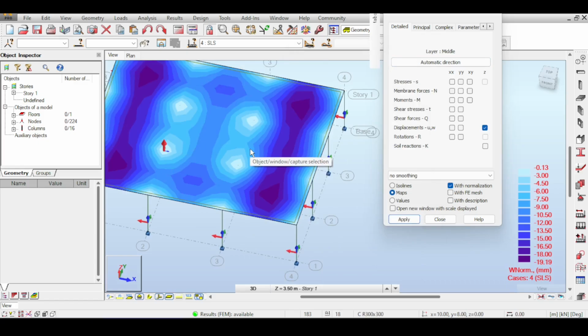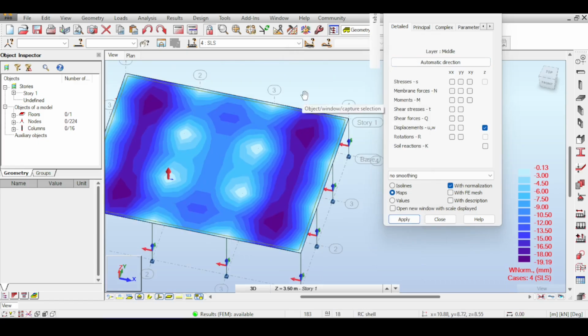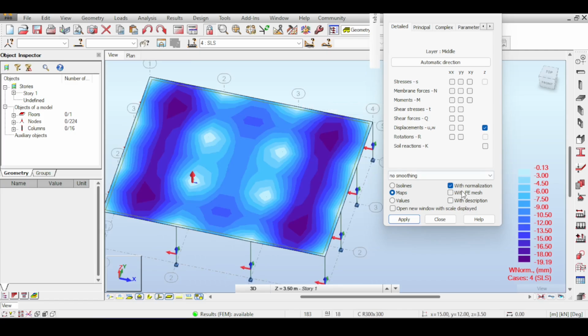You have your own codes that could help you. Our dear subscriber Donald Khanye mentioned a question that I will address later about what this U is. In this case, in our view here in maps, the U here is the short-term elastic deflection, calculated, of course, using the reduced inertia, 0.25 I gross. Please notice that the long-term deflection is even larger than this, because concrete has long-term deflection calculations that sometimes could be twice whatever you get in the short term.